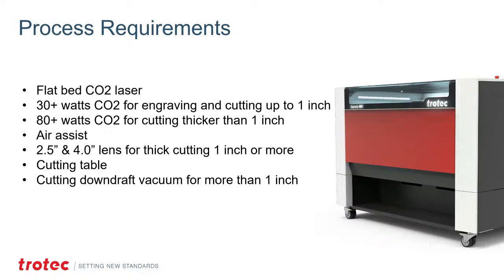Requirements: this is mainly a CO2, I should say. There is the possibility you can actually cut some versions of foam with a fiber laser. I've had decent luck engraving and cutting it with a fiber laser, but I'm not going to get into that too much because it is not that popular and it just doesn't work as well as a CO2. But just so you know, a fiber laser will work with especially the grayer polyurethane foams, and I've even cut it with a fiber laser. But like I said, it's not as pretty of a response as a CO2, so I'm not going to really showcase it, but I did want to mention it.